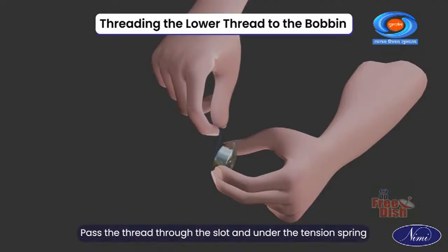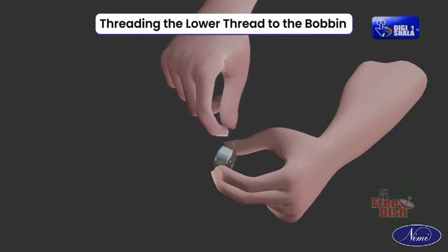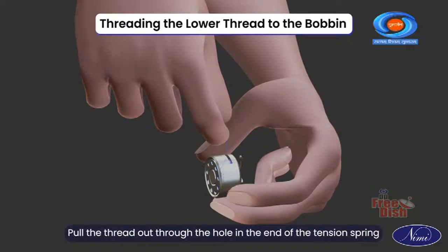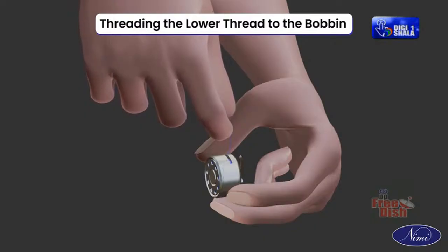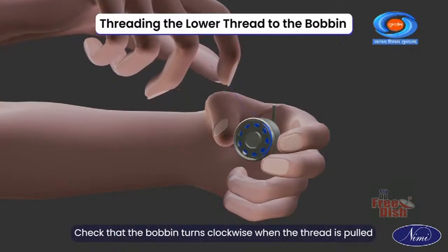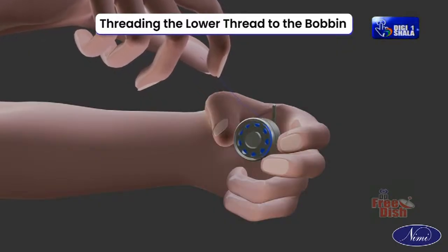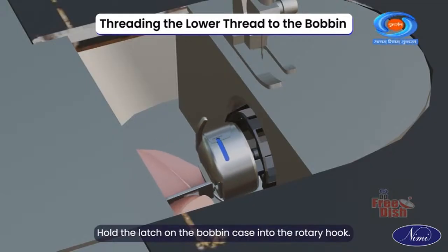Pass the thread through the slot and under the tension spring. Pull the thread out through the hole in the end of the tension spring. Check that the bobbin turns clockwise when the thread is pulled. Hold the latch on the bobbin case and insert it into the rotary hook.